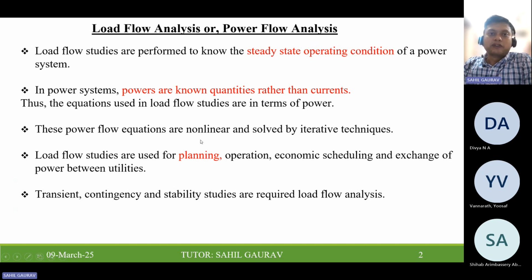What is the purpose of load flow studies? Load flow analysis or studies are performed to know the steady state operating condition of a power system. In a power system, powers are known quantities rather than currents, and therefore the equations used in load flow studies are in terms of power, not currents. These power flow equations are nonlinear in nature, and we solve them using iterative techniques.